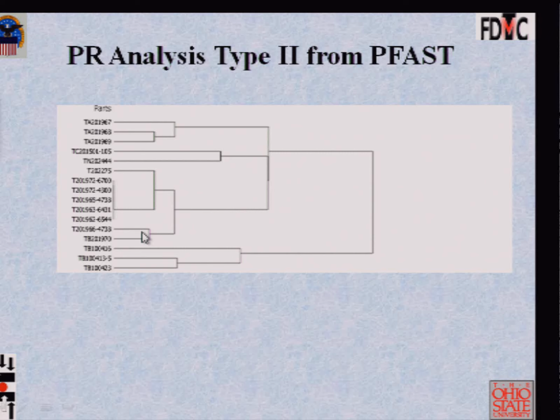Again, this may be a little too much to swallow. The point again is that you need to look at families of parts. You need to look at which value streams are identical and which ones are similar. But you need to maintain the uniqueness and the identity, because all of these value streams become kits that become sub-assemblies. And if parts are missing, you are not going to be able to complete a sub-assembly. So I think that the authors of the value stream mapping book are making major assumptions just because their method cannot handle complexity.